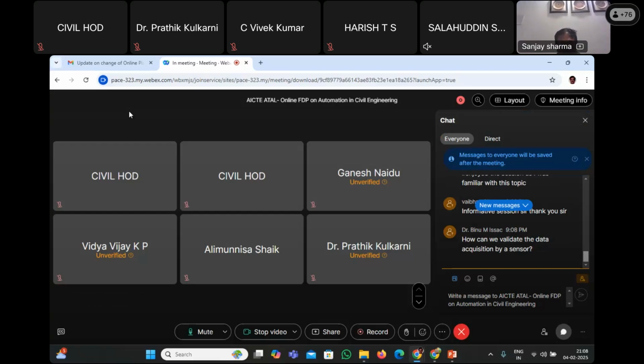So condition assessment, fine, you base it on that, but then the stability part is again related to your design also, because for what purpose you are carrying it out should be understood. If it is repair and rehabilitation only, fine, but if it is for retrofitting, then I think you need to carry out the complete analysis also.